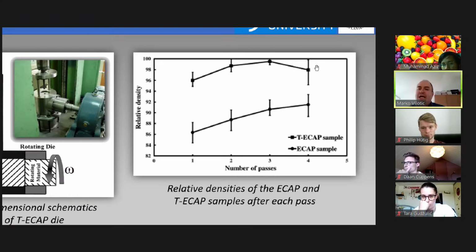There is one thing I will show you now about SPD. We talk later, we say if I reduce the grain size more and more, I will have better performance. Now, you cannot do it forever. You cannot do it indefinitely. At some point, the defects in the material will be more and more pronounced. So at one point, you will have a drop in performance.